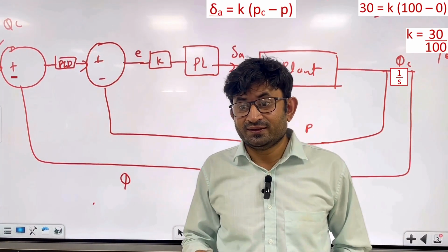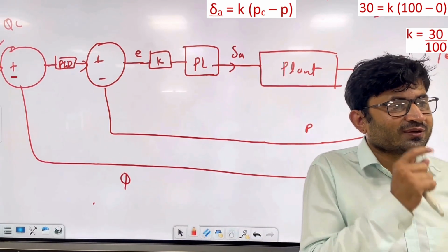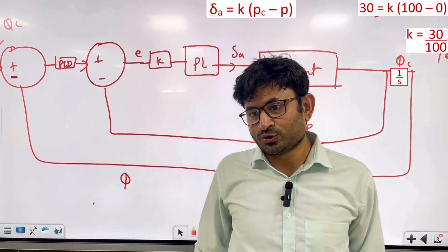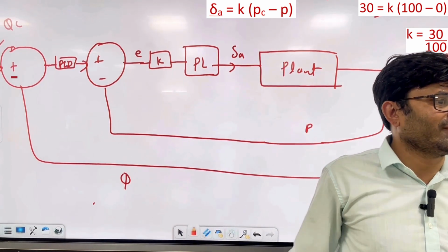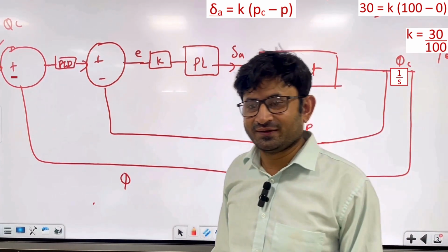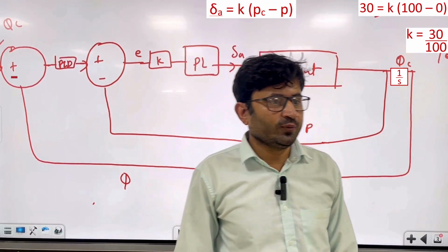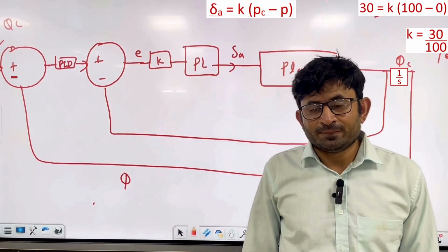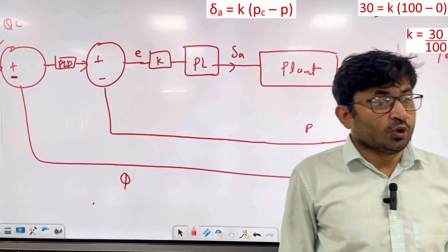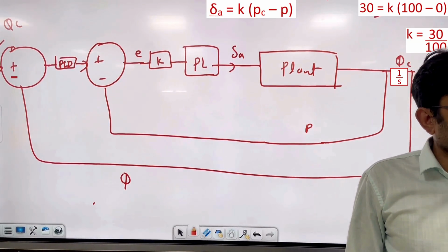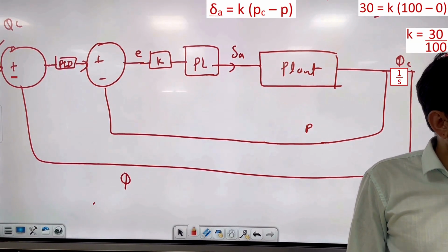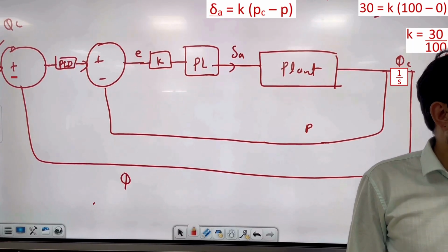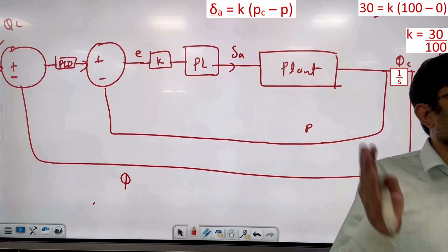So when you fly, you will see there is one mode called stabilization mode. That will reduce the workload of a pilot basically. And this is a very good mode. If you are a very new beginner, try to fly in stabilization mode. Then don't think that stabilization is fully autonomous. It's just part of the things you have automated. But what about the throttle? Throttle you still have control of.